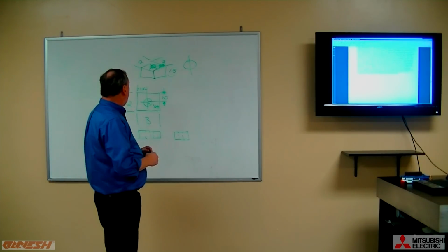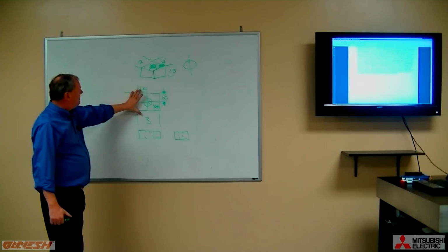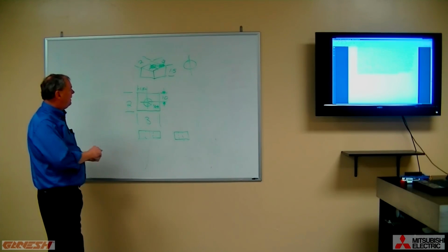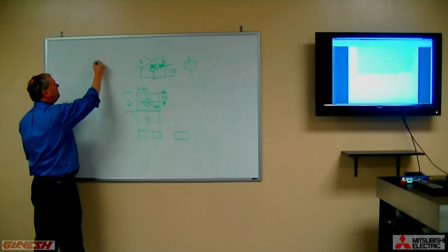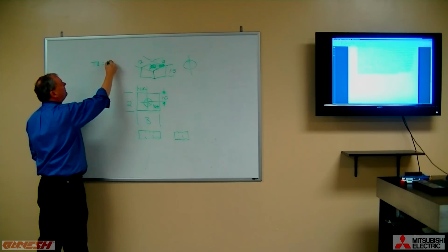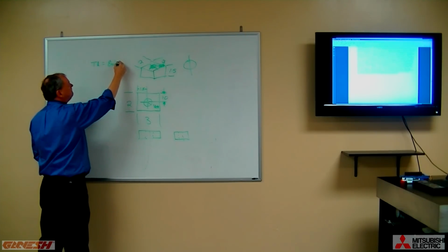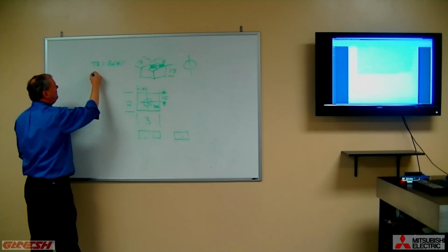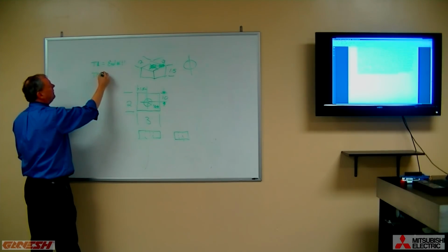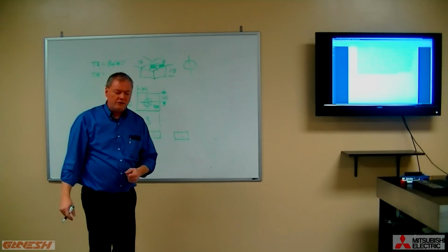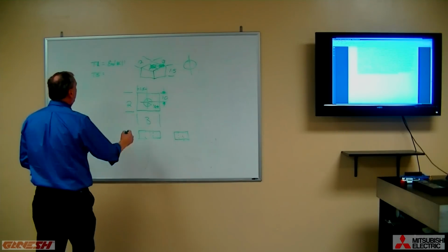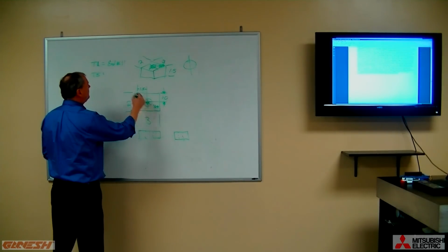What we want to do now is a 2-tool cutting operation on this part. Let's take an end mill and call it tool number 1. I'm going to create a tool and call it tool number 5 for lack of a better number. They don't have to be used in order. Tool number 5 is going to be a drill, to simply drill this hole.